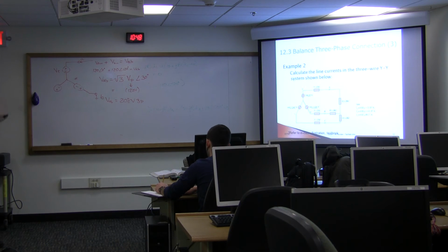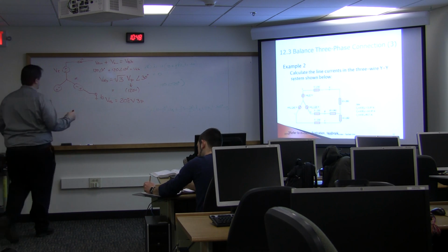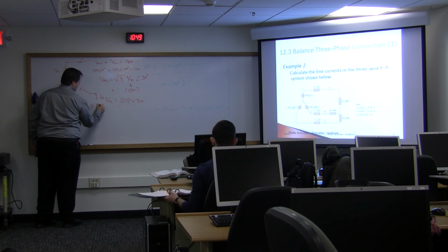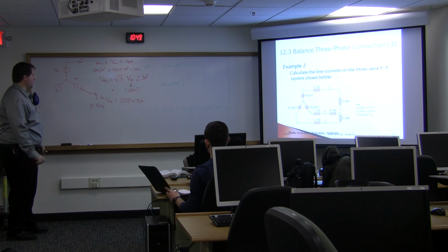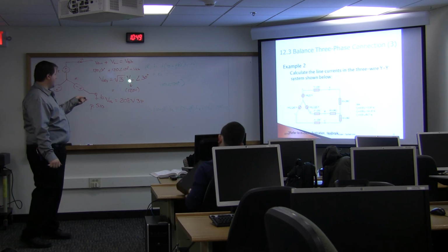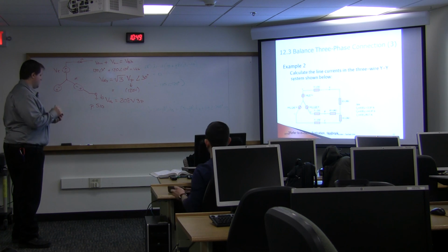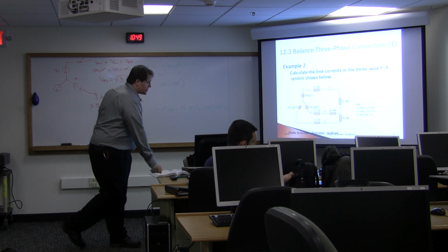And it comes from this, that the supplies are connected in a Y, but we typically measure between two of the lines. So we measure the line voltage, not the phase voltage. Again, this is one of these terminology things that gets three phase a little bit confusing. The page number for that is 510, so definitely look through that little derivation. It's very straightforward, and they just show the calculation steps. Again, it's just combining these in Cartesian and substituting the phase voltage as the magnitude. All right? So we'll start with that again.